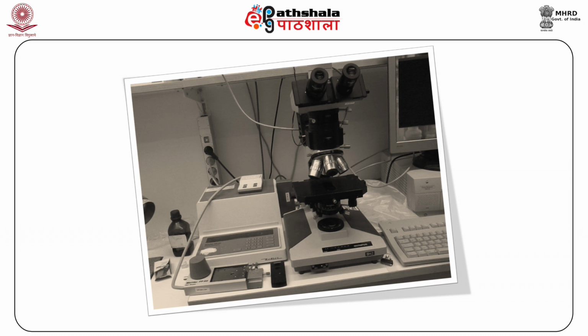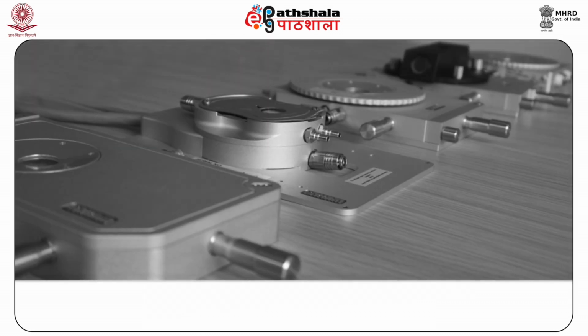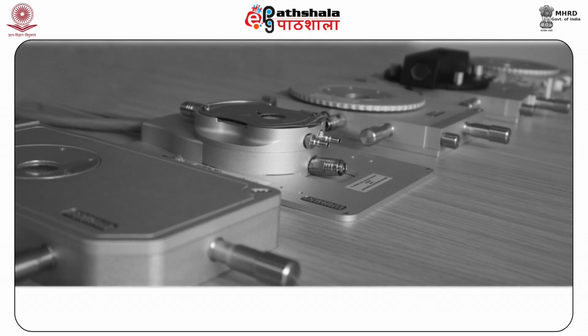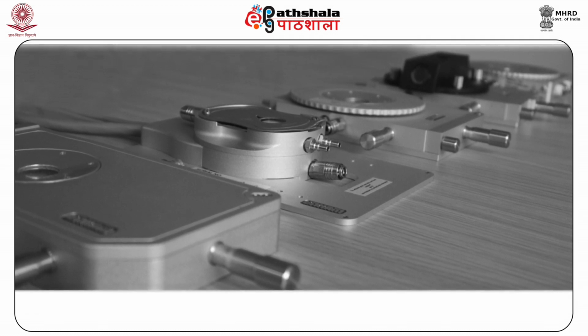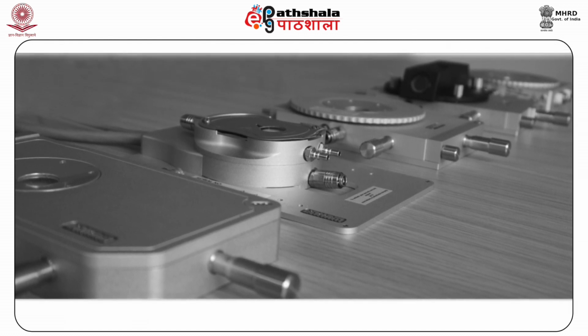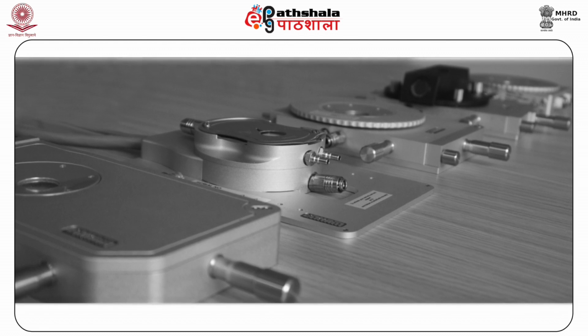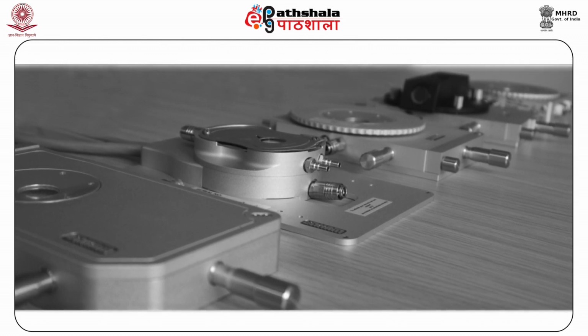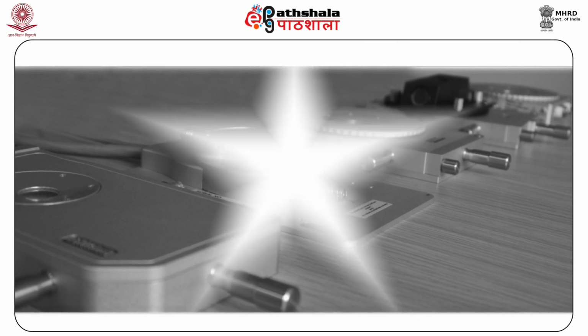Thus, material phase transition information, qualitative as well as quantitative, can be determined. It has a furnace with a heating element beneath and above the sample, which guarantees outstanding temperature uniformity in the sample. In the method using the hot stage microscope, the glass sample is immersed in a high boiling liquid.